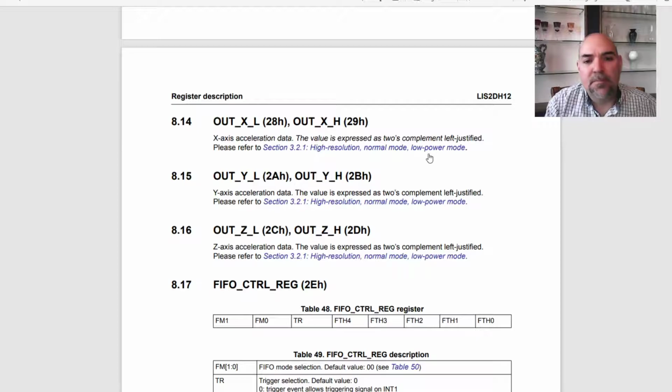But the idea there is we're getting this data as a 16-bit two's complement value. Two's complement means it can have negative numbers and positive numbers, and it's telling us an integer value that could go negative when the acceleration is in one direction, positive when the acceleration is in the other direction, and we've got 3 axes of that. So we could set this device up and then read that data out of there and know things like,